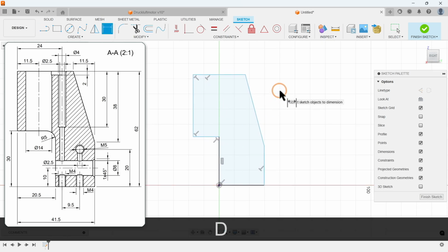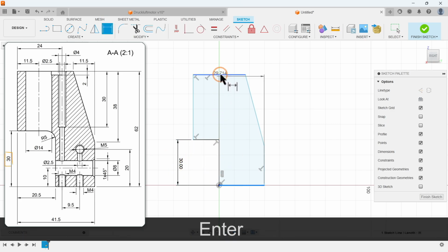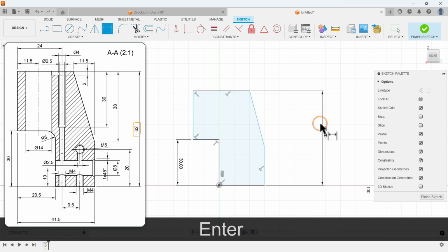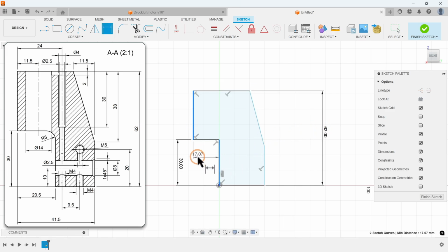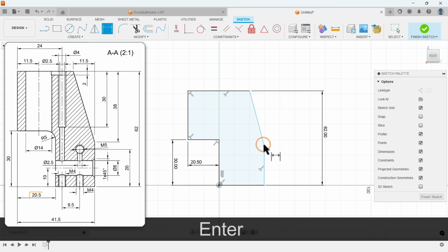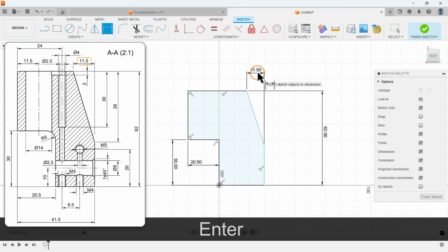By starting in the side view, we can capture a large part of the contour in the first sketch. This allows the engine block to be constructed with relatively few elements, increasing clarity and making later adjustments easier. Afterward, we'll add all the missing dimensions until the sketch is fully defined.